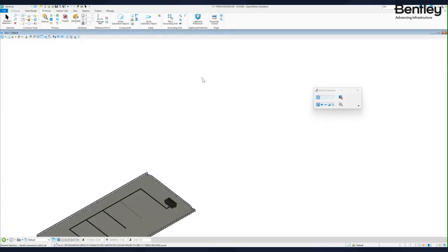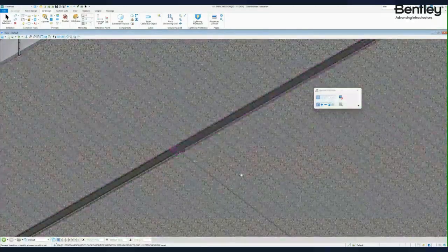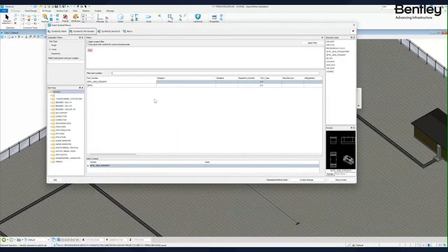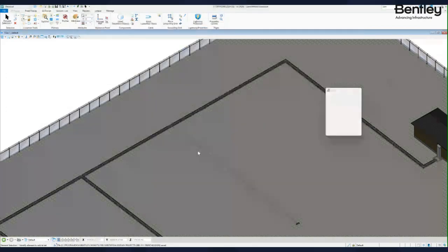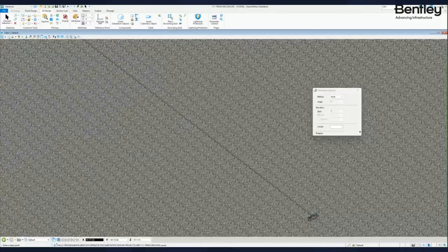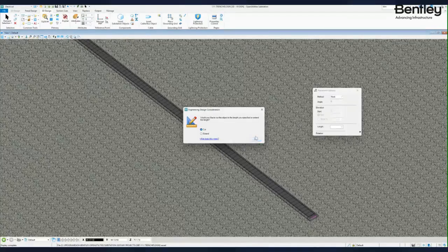One of the examples will be trenches. That means that I have my trench system here, and I missed it, and I didn't add the last portion of it. And I can simply go to Insert Substation Object, go to Repeating Parts Type, and go with my 3D trench. Just place the symbol, click somewhere here using the hook points here. And as you can see, it's having the gap here.